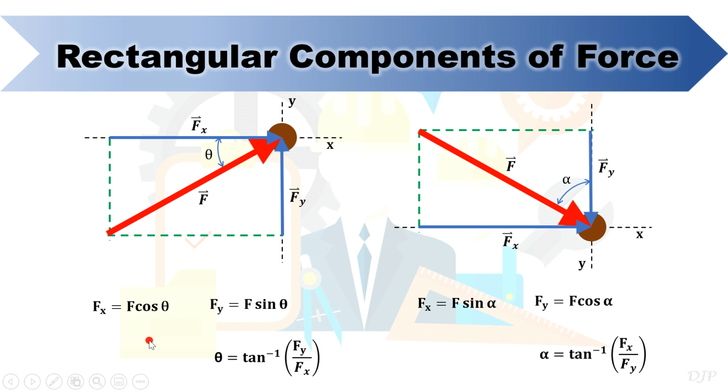To form the right formulas or equations that you will need, you must draw carefully the direction of the forces and be mindful of any given angle of inclination. As we did in the previous slide, you may draw a new diagram by triangle rule before applying trigonometry so that you will be guided as to what appropriate trigonometric function you should use and how you can formulate the needed equations.